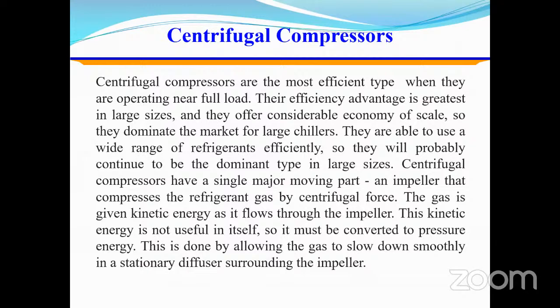Their efficiency advantage is greatest in larger sizes, and they offer considerable economy of scale. So they dominate the market for larger chillers. They are able to use a wide range of refrigerants efficiently. So they will probably continue to be the dominant type in large sizes.